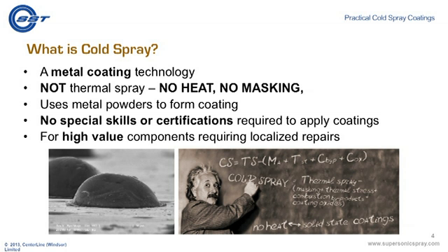Cold spray is a metal coating technology. It's not thermal spray. There's no heat or masking required. You're going to use metal powders to form the coating. There's no special skills or certifications required to apply coatings, and I'm going to show you the equipment in pretty good detail. It's primarily aimed at high-value components requiring localized repair. And for you that are in the remanufacturing business, this is perfect for you.